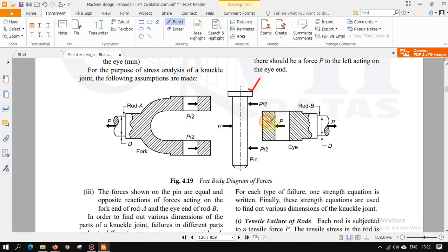So what happens is that in this section it comes with a UDL section. Now why does it come? Because this surface stays in entire contact, but this surface doesn't come in entire contact. That means there is some amount of deflection, for which we cannot say that this is UDL, that is uniformly distributed load. Same goes for the down system. So in both these cases we are dealing with VDL, that is varying distributed load. And where we come in full contact, we state it as a UDL.